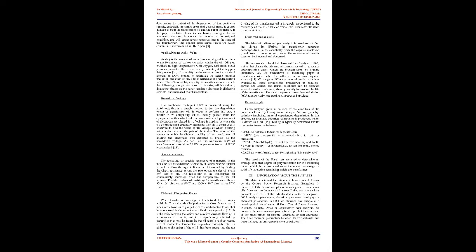Acidity/neutralization value. Acidity in the context of transformer oil degradation refers to the formation of carboxylic acids within the oil. Oil gets oxidized at high temperatures with oxygen, and small metal particles present in the oil are usually the catalyst that triggers this process. The acidity can be measured as the required amount of KOH needed to neutralize the acidic material present in 1 gram of oil. This is termed as the neutralization value.